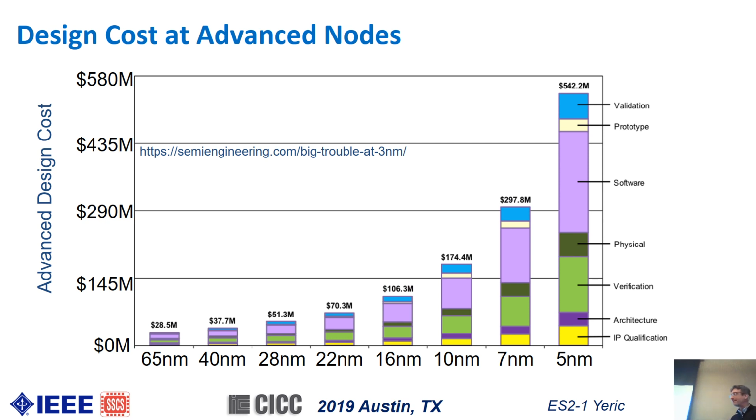So just as a summary, for chiplets, one of the really attractive things is instead of doing the design effort to shrink an entire SoC, let me just spend the 500 million kind of number just on my cores, and then I can reuse a lot of stuff that doesn't necessarily need to shrink anyway and save a lot of money. So cost is king, and you can see the wave of chiplets coming just from economics. It's definitely going to happen.